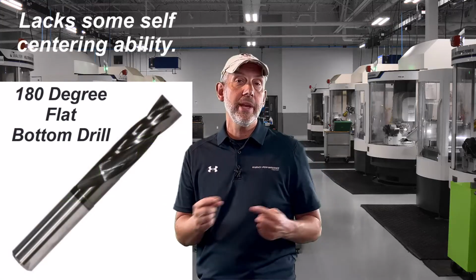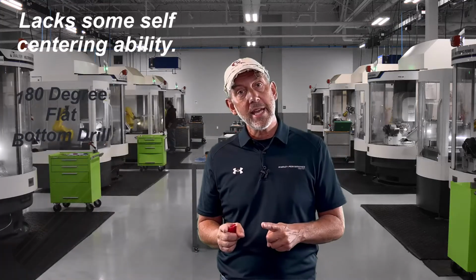Now, that I said that doesn't mean you want a 180 flat bottom. That's not going to work because it's going to bring in other issues. But what I'm saying is you don't want a 118, you don't want a 60, you don't want a 90-degree point for, say, some Inconels, Hastelloys, or some very hard materials.